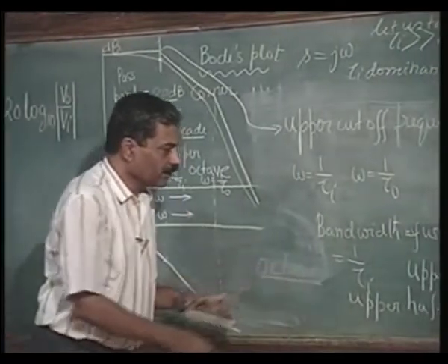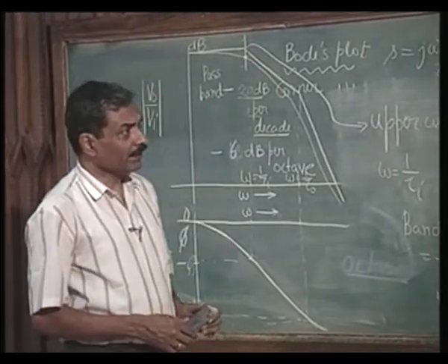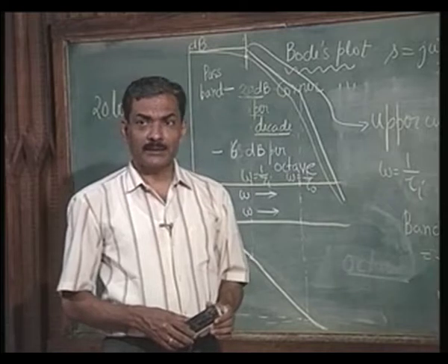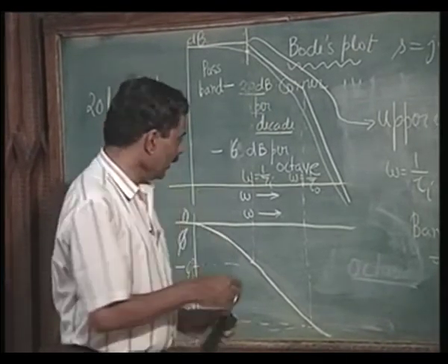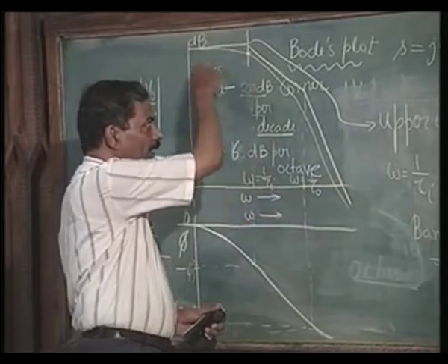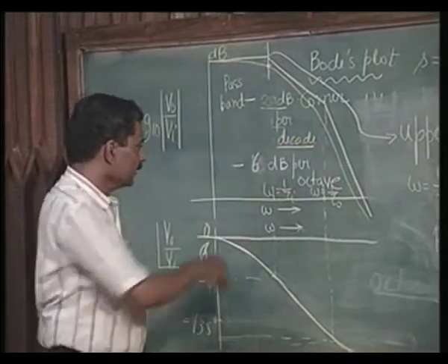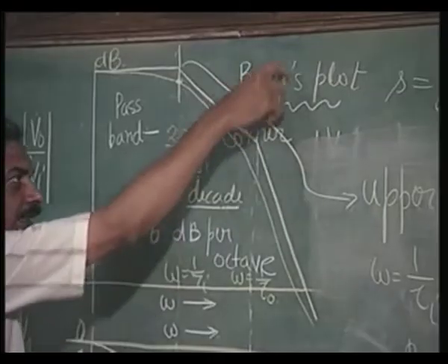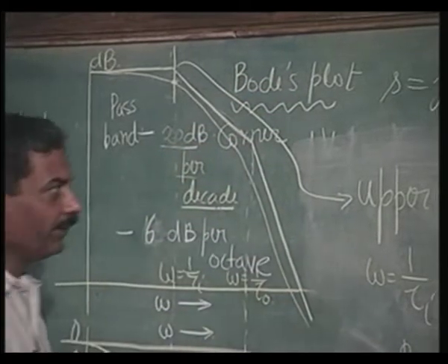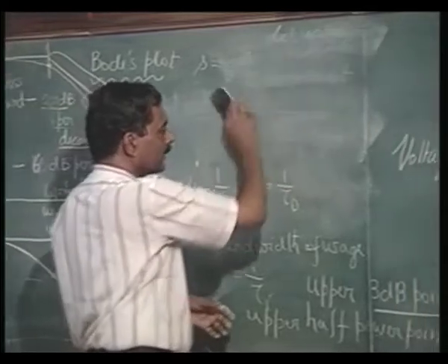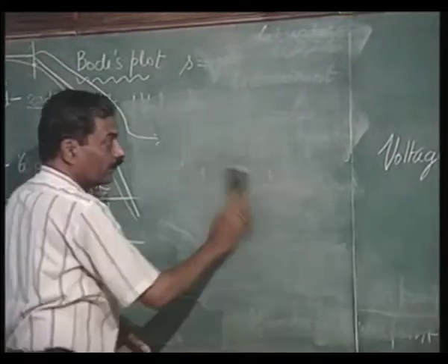Now, as far as tuned amplifiers are concerned, basically the load is selected in such a manner that this particular frequency response characteristic is not like this, flat from the low frequency end coming down. It is starting with 0, reaches a peak at a certain point and comes down like this. So, the tuned amplifier characteristic is different from these wideband amplifiers or low frequency amplifiers.